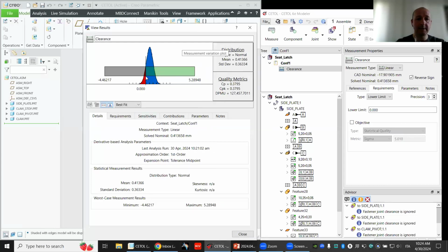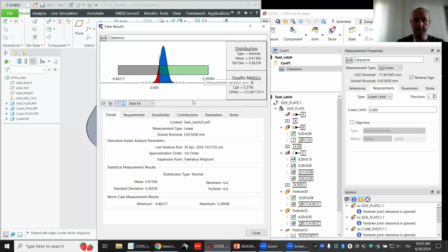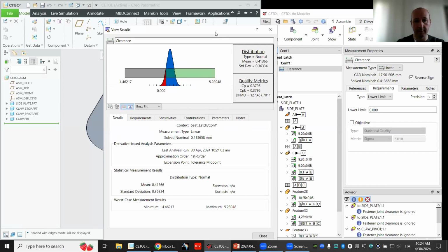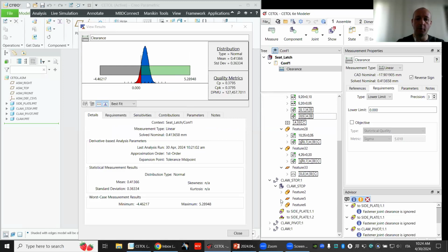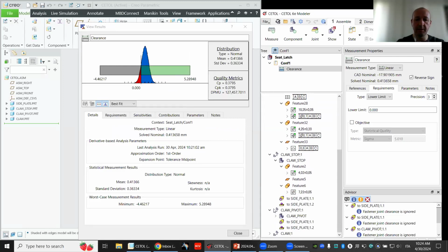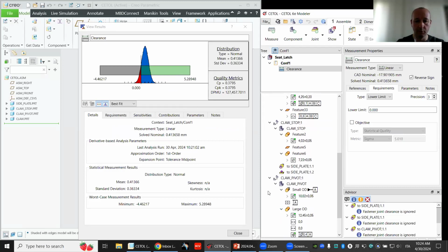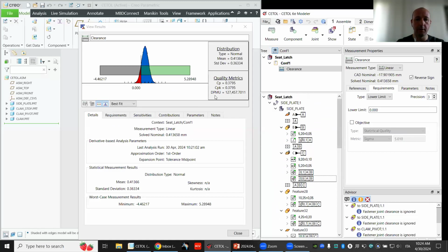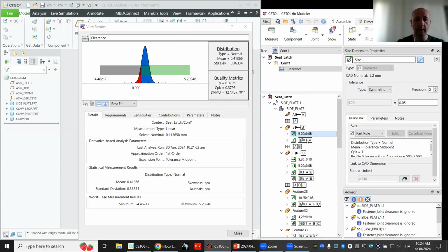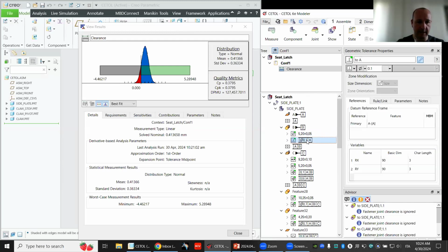As you can see here, in a few minutes we solved a very complex tolerance propagation model, because there are more or less more than 50 tolerance contributors in this model. We are talking about a full three-dimensional tolerance chain with both dimensional and geometrical tolerances inside.